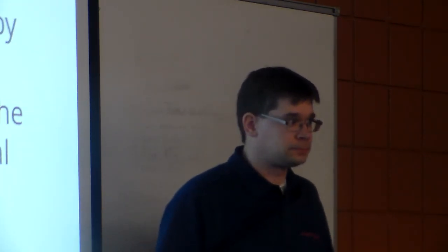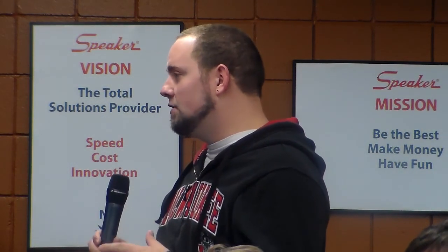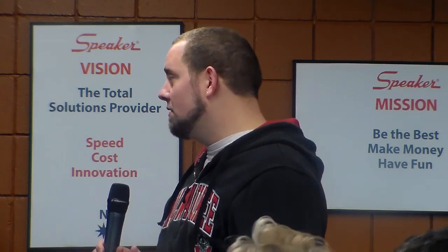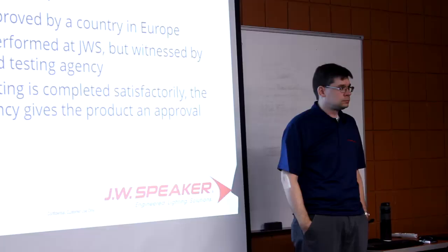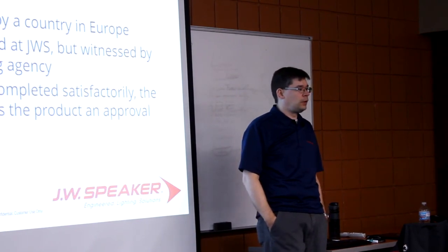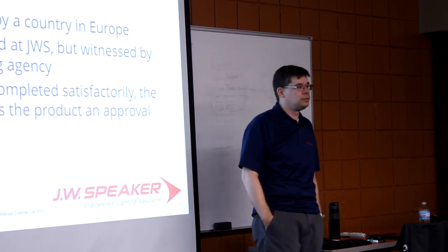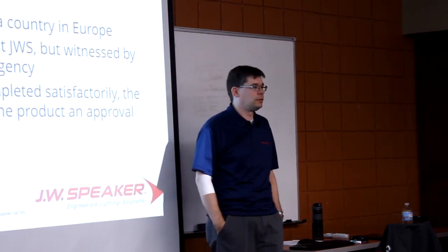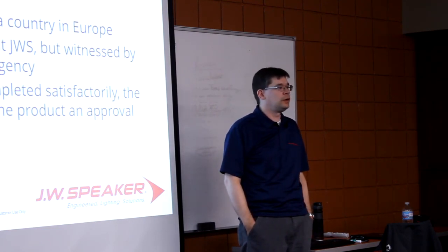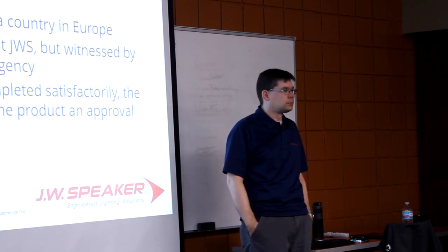So, talking about FMVSS, we talked about there's the photometry as well as some environmental or mechanical regulations. Does ECE also have any sort of environmental regulations, and do those also need to be witnessed by the testing agency, or is it just the photometry? There is some limited, I would say, environmental testing that we have to do. A lot of it's dealing with the type of material we use. So we do have to do some basically deterioration tests on the lenses. But it's mainly photometry.